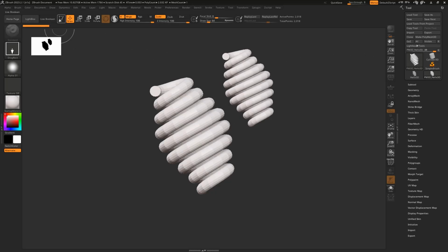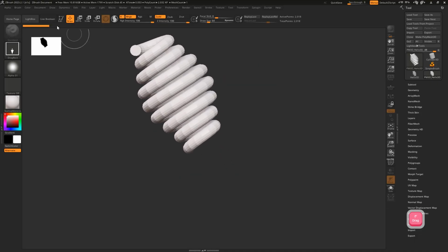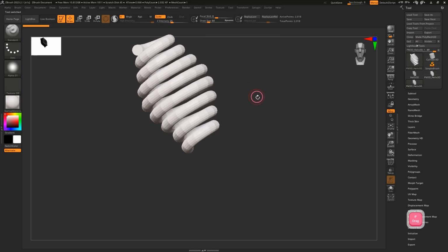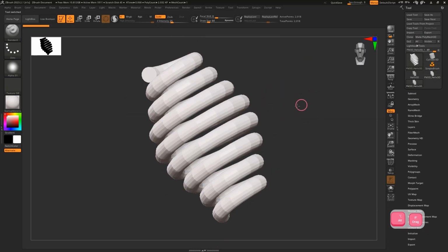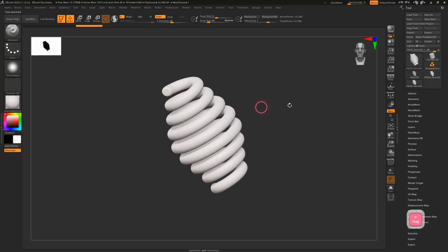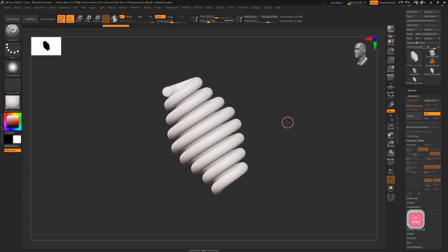It's not going to work. You really need the edit button to make it work. So it's a good thing you made that mistake. First we do this, and then we do edit, and then we do make polymesh. Perfect. Now if we just make it a little bit with more subdivisions, check, delete lower, and let's go.